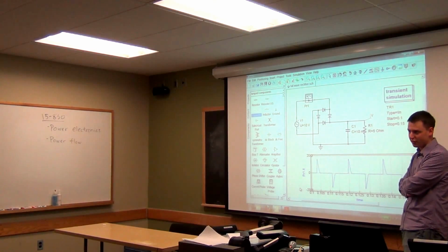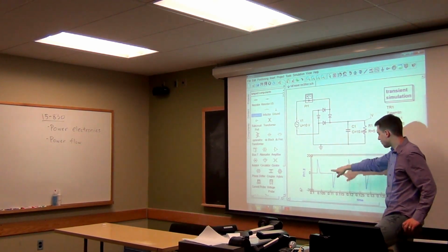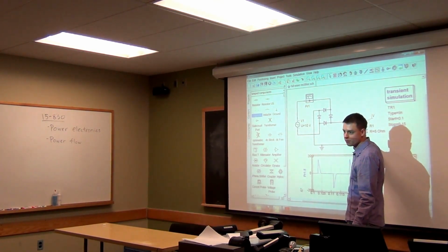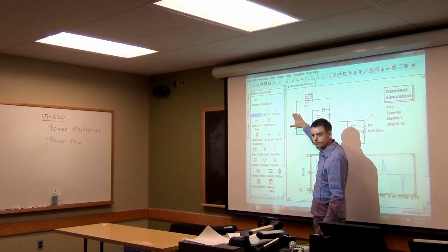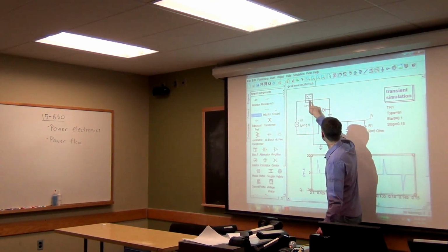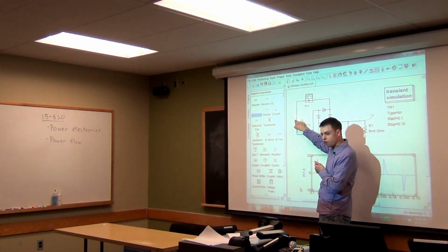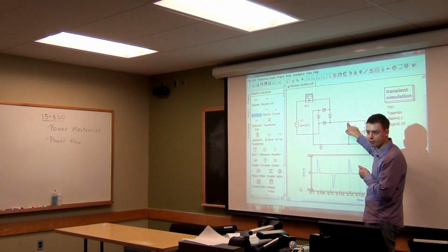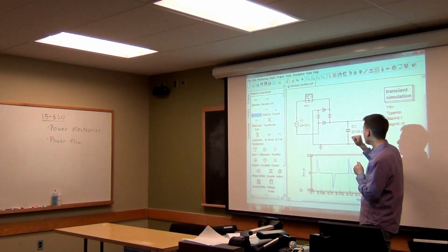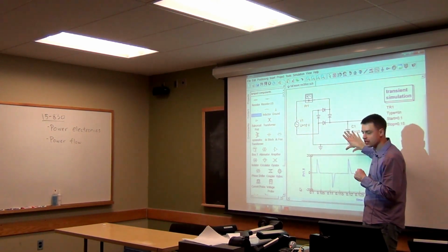Now what's happening here is the following. This capacitor, remember, stores charge. So during one cycle, say it's gone through a cycle, it was putting power this way, and this has built up some positive charge. The source switches, and so we want a situation where we're providing power that would flow this way, right? But initially, when this just becomes positive, the voltage here will actually be lower than the voltage that we have on our capacitor. So it won't flow that way. It would actually want to flow the other way, but it's being blocked by the rectifier, fortunately. So at first in the cycle, actually no current will flow from the source. All the current we get is being provided by our capacitor.